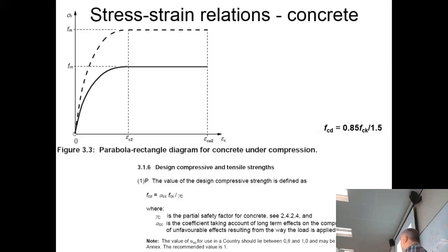There is only sort of one way, so it'll be based upon the Eurocode, but then different people have interpreted the Eurocode slightly differently and have their own set of formula for designing. You will find that they're all largely the same. I'll show you some examples of what looks different. But yeah, so in Europe you're expected to use Eurocode, and you're expected to use this stress block technique. The only time you would use different is if you went to like America or anywhere else that they use a code outside of it.